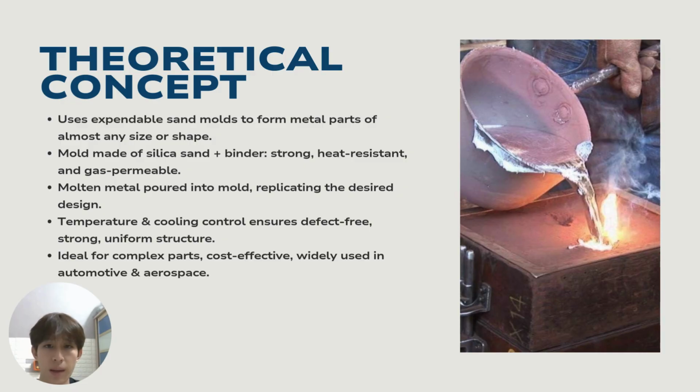The process starts by creating a mold from silica sand, which is mixed with a binder that gives it strength and thermal stability while allowing gases to escape. Molten metal is then poured into the mold cavity, replicating the desired design, even complex internal features.